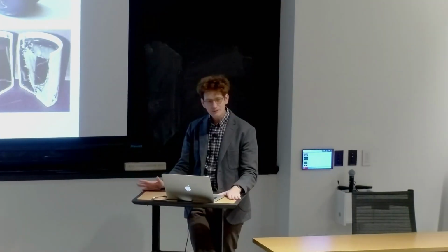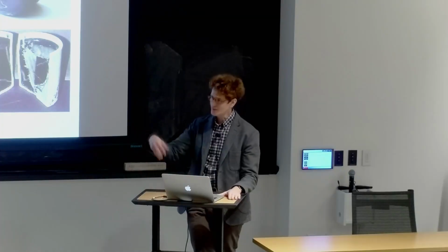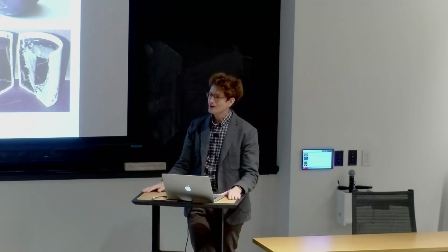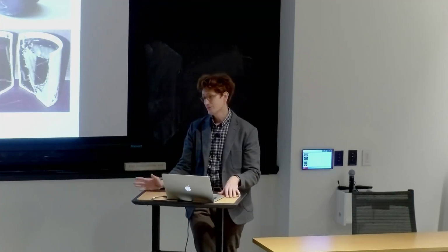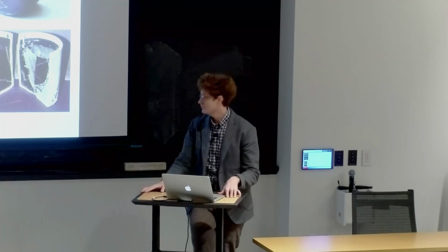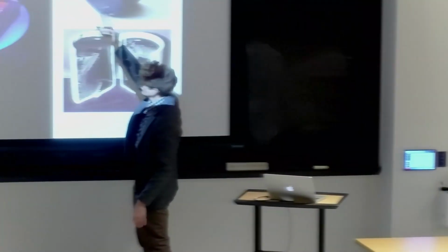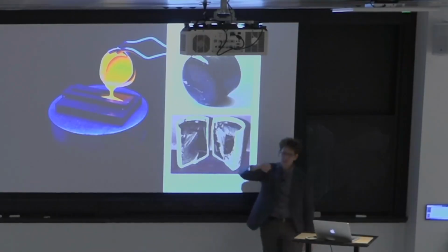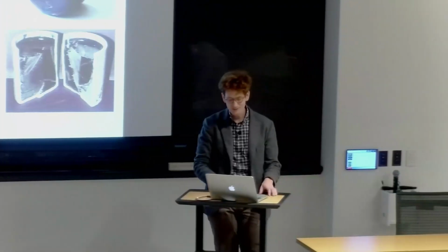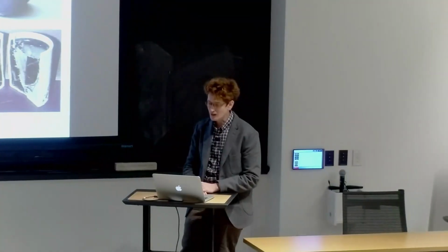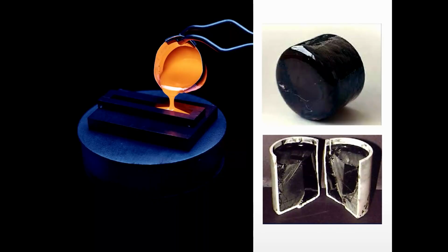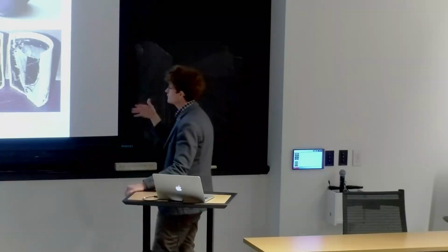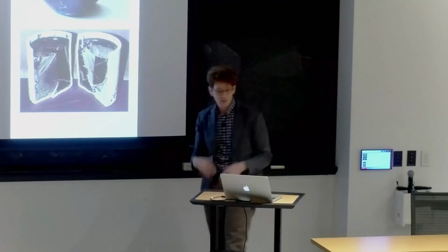So it turns out some of the elements are volatile at temperatures lower than the melting point of glass. So you try to add them in and they just boil out. Other problems are some elements actually precipitate at reasonably low concentrations in the glass. So you'll get these crusts forming on the outside, so it's not really suspended in the glass. And some elements cause corrosion processes in certain kinds of glasses, with lots of glasses. So lots of work continues to be done on glass-based vitrification.